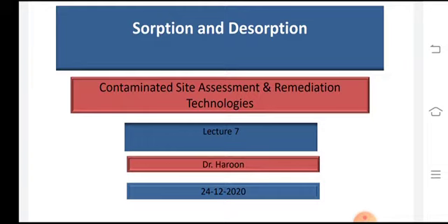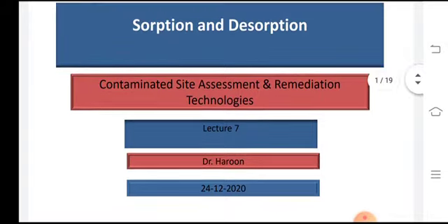At the initial stage, at the boundary where the solute is entering, we have a typical quantity of solute. For example, chromium with a concentration of 10 milligrams per liter is entering into the soil. Now in the soil, it is going to exist in the aqueous phase or in the solid phase. So it will give us different concentrations for different times as well as different locations.